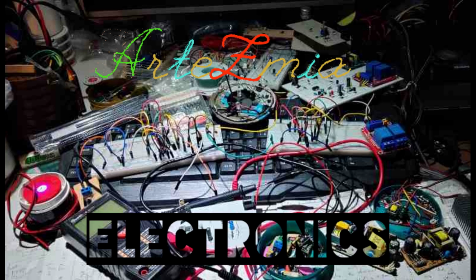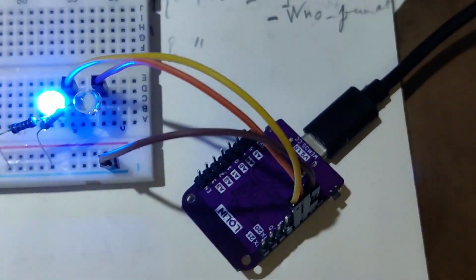Now we're going to test our boards with a little circuit on a breadboard. We have two LEDs, each in series with a 220 ohm resistor. Each positive pin of the LED will connect to the GPIO of the board, and the resistors are connected to ground. We will power the boards through the USB port connected to the computer.